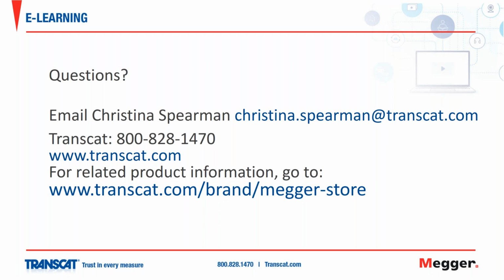I'm not familiar with that application. Jeff, do you have any comments on that? Yeah, we're always open to looking at something that may be a new application or something that's never been asked before. Certainly, it does violate the general caveat about testing on electrically dead, disconnected items. However, you're looking at a live item that doesn't have a whole lot of power behind it. And so you may be in a gray area where possibly it would work, but that would require us to take a closer look at it. And I'm hoping for the sake of the caller that the tester can meet a 1 volt criterion, but it should be examined separately, and we'll be glad to do that.